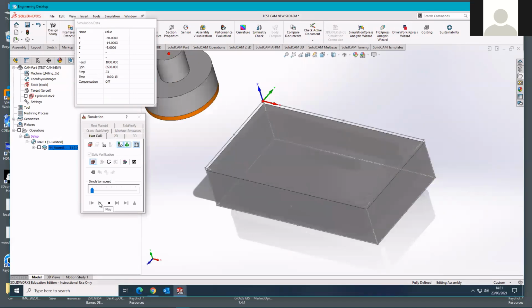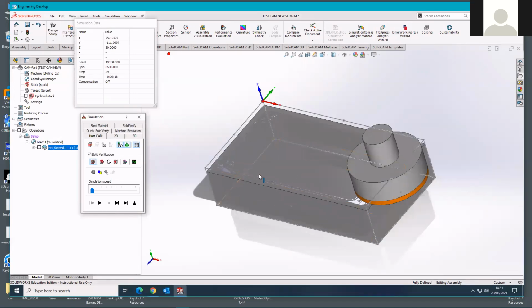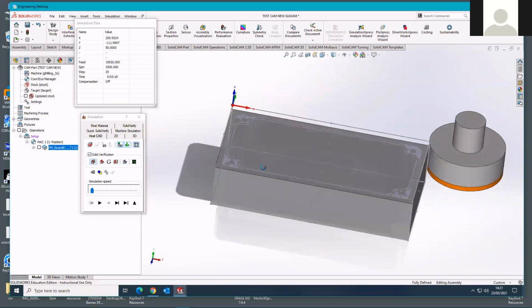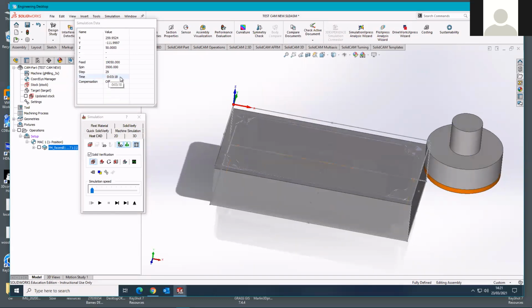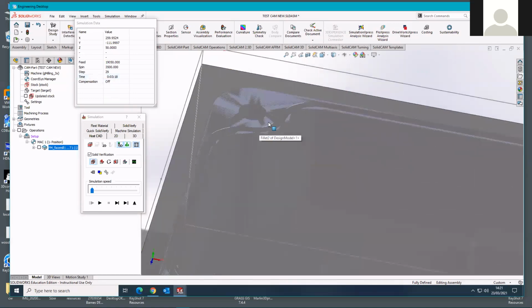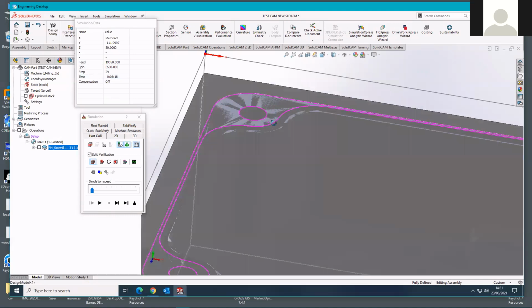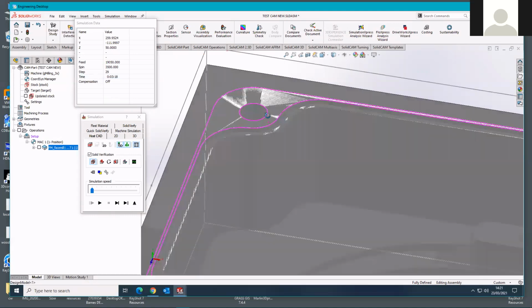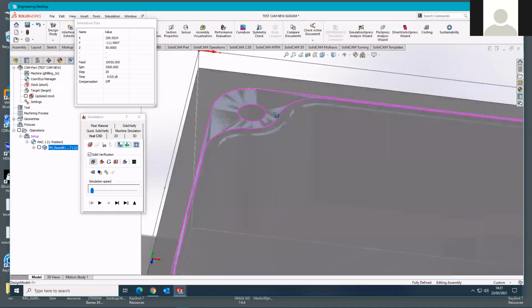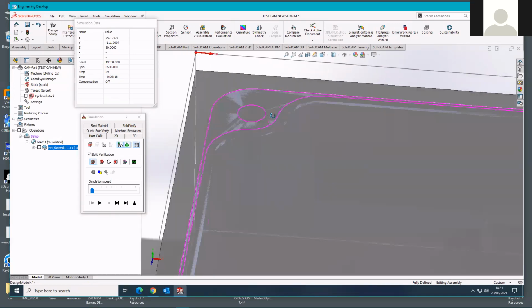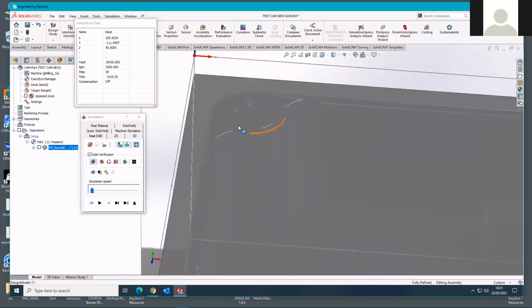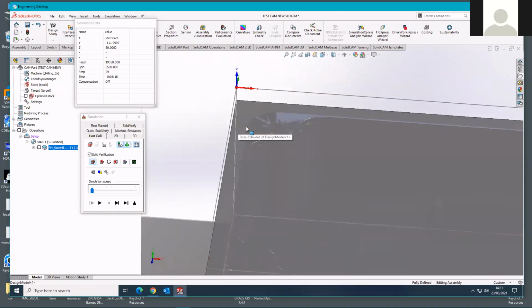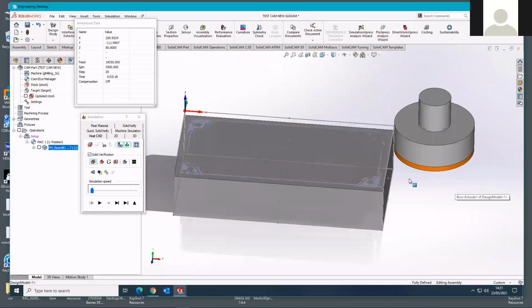The big face mill comes in and hatches backwards and forwards across the part. It gives me a running total in terms of the time. If I zoom in a little bit, I'm getting that slight battling for supremacy between the two surfaces there, which I'm going to take as my indication that we have actually reached the correct level. So yeah, I'm broadly happy with that.